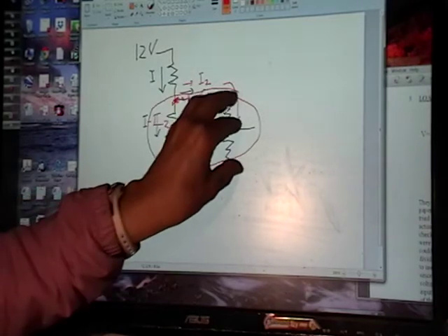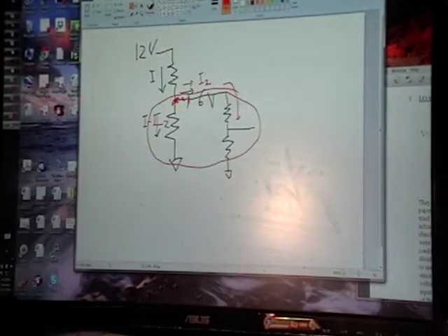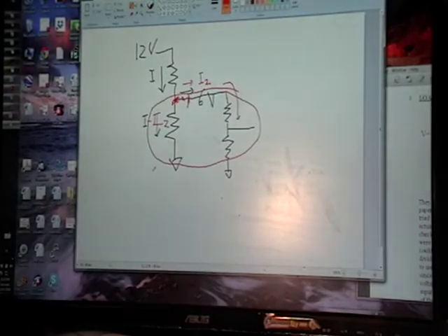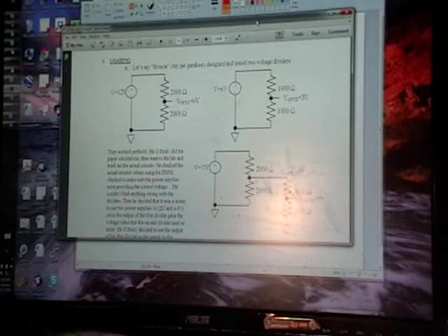When whatever circuit you're connecting your first circuit to takes some of your current and changes the behavior of your first circuit, that means your first circuit is loaded by your second circuit, or your second circuit is loading your first circuit. And so this is an important concept, and you'll see it, maybe when you're doing your senior project,